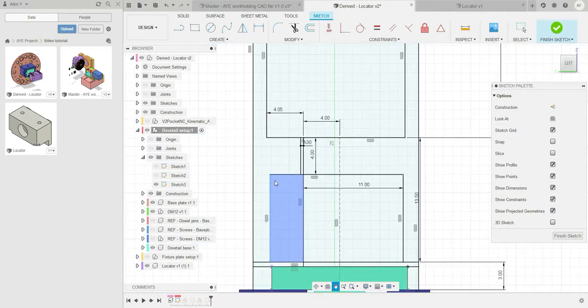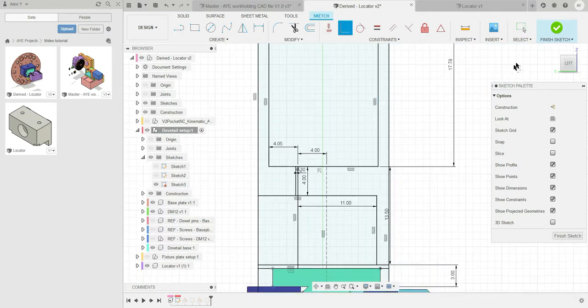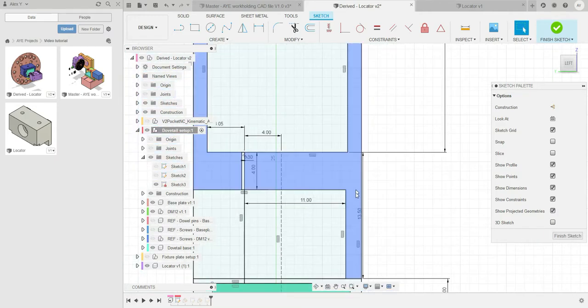On this side you don't need to worry about it, so you can actually delete that and go up to the edge. So the spindle will come in here, you'll machine this face away first, and then that means for this cut in here the spindle can come in and take out the material without hitting.